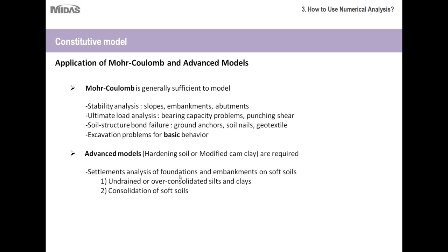So once again, usually it's a combination of the modified Mohr Coulomb model and the modified Cam clay model that are used to do your settlement or drainage type analyses. And then deep excavations for detailed behaviors. So if, for example, deformations or settlements are of particular importance to you, then the modified Mohr Coulomb model is typically your best option, just because there are certain variables that the constitutive model takes into account that allow you to better simulate this detailed behavior.